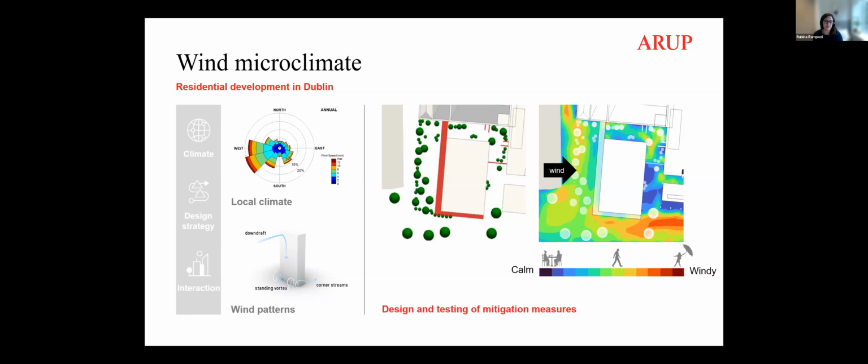And so they are often required to be addressed as part of the planning process. This is very frequently done with numerical simulations. The advantage of using numerical simulations, as opposed to, for example, understanding how the wind works around a building in isolation, is that we can really account for the effect of the surrounding buildings, the different wind directions and speeds, and also the effect of landscaping and hard landscaping elements that have been designed. We can also support the design by trying to find mitigations and elements that can be integrated into the design itself, but also be helpful to reduce windiness in sensitive areas around the development.